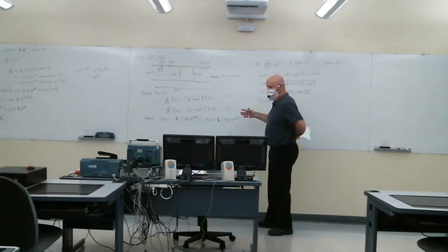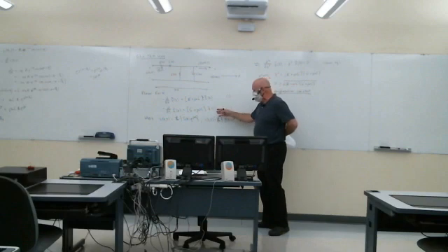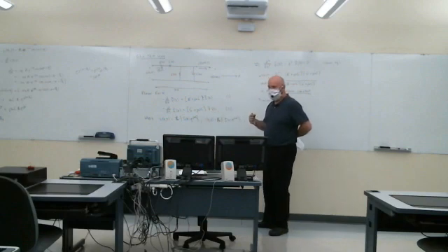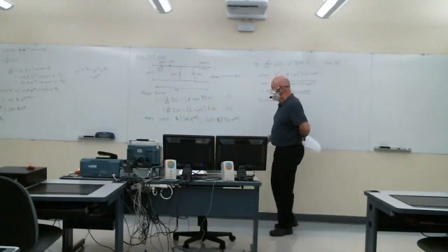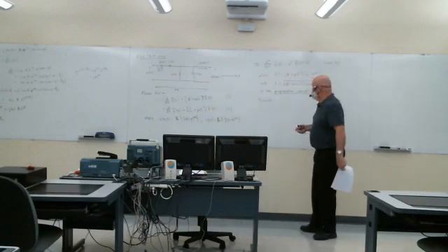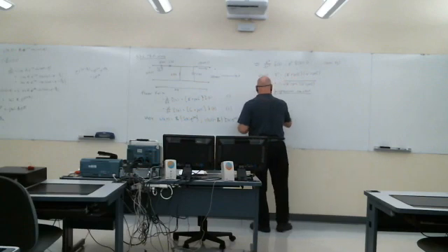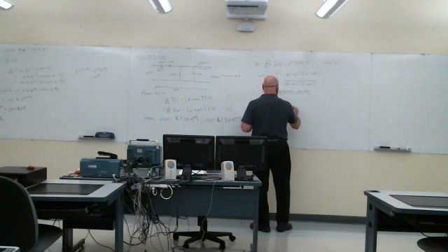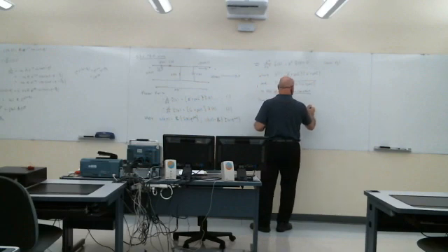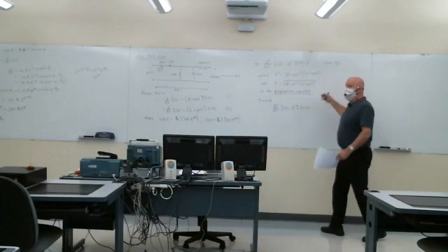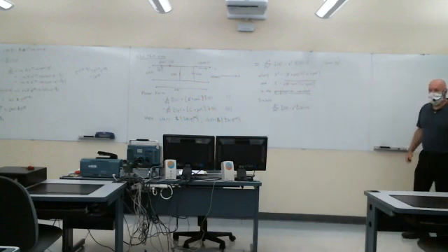You could do something similar with the second equation: take the derivative of it with respect to z. On the right-hand side, we'll get the partial of v with respect to z. Take equation 1, plug it in, and you'll get a wave equation for the I phasor: V minus gamma squared I tilde z. Actually, it's the same wave equation, same propagation constant.